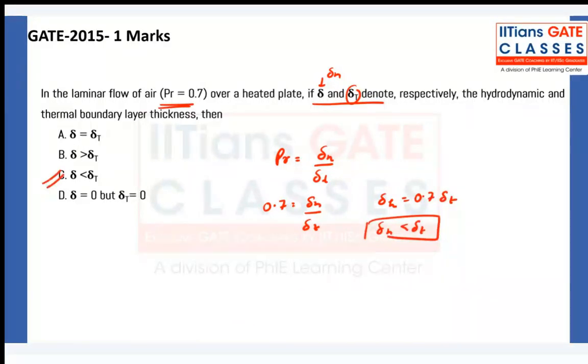You can use that, of course. Look, again, you have to do the same. It's the same thing. Look, Prandtl number to the power -1/3, 1 upon 1.02. You can use the whole equation, delta T upon delta H. Let us assume delta H as 1. Then Prandtl number to the power minus 1 by 3 is equal to thermal upon this.